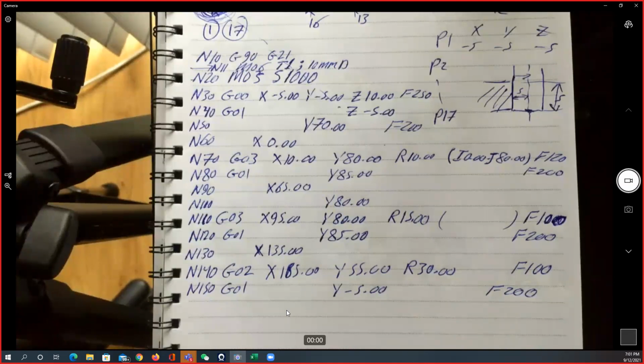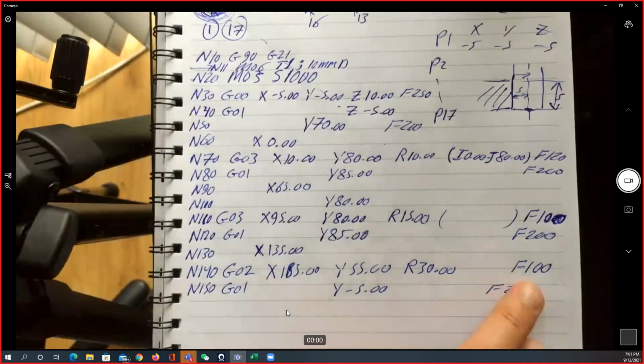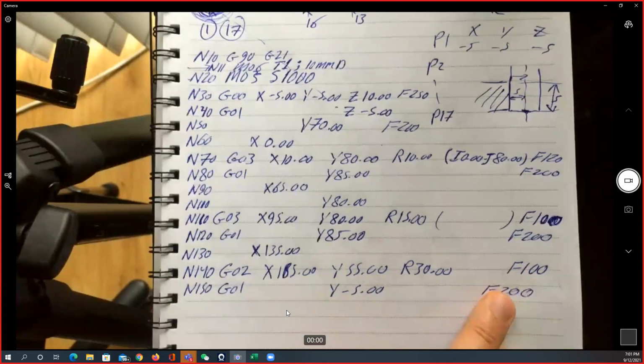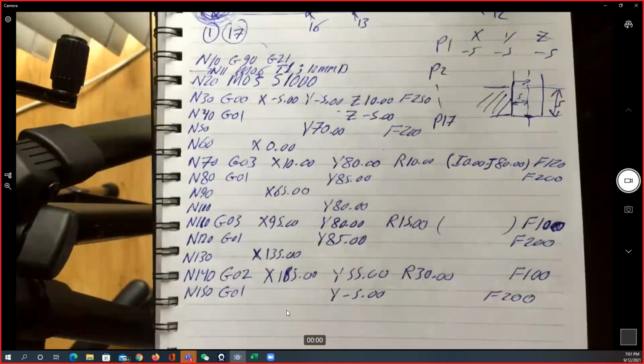So we need to make multiple calculations until we get the optimum time with the optimum cutting speed. That's why I just keep changing that. I would like to have good quality, but I would like to shorten the machining time. Usually the average time will depend on the cutting tool type and the material we are cutting.